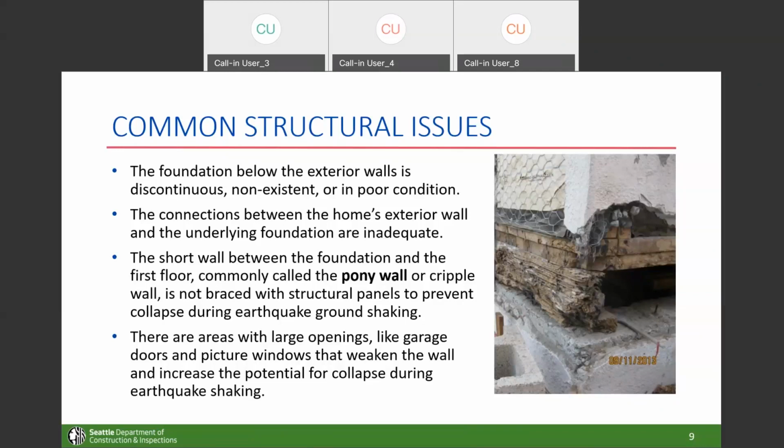Those are again kind of iffy because we just don't know exactly how they were constructed. So often the Project Impact drawings have to limit the foundation to a specific height or a specific type, to make it work as a prescriptive plan set. If there are other items, retrofits are still very possible, but it may be time to hire a professional or an engineer, or do a voluntary seismic retrofit in another permit.